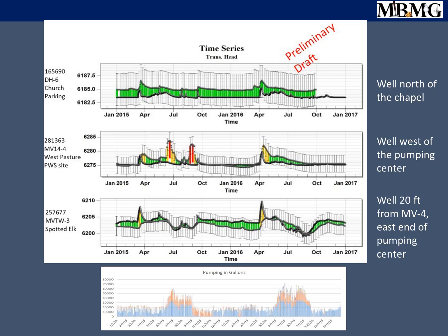It looks like the aquifer is recharging in September, though. Where do you see this? In both years. Down here on the bottom one, yeah, it looks like in September it goes back up after the irrigation season. Yeah, it's like once they shut down, well, lower the pumping rate back to winter levels, then the aquifer recovers relatively quickly. And we don't typically get a whole lot of rain in September, so it's not that that's causing the recharge.